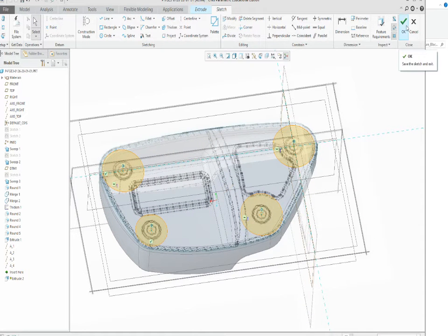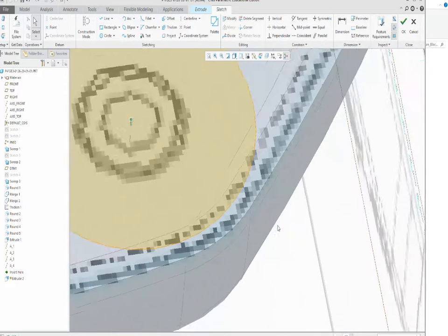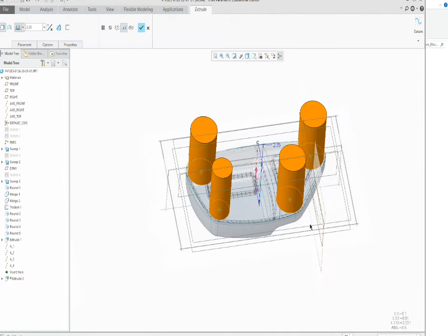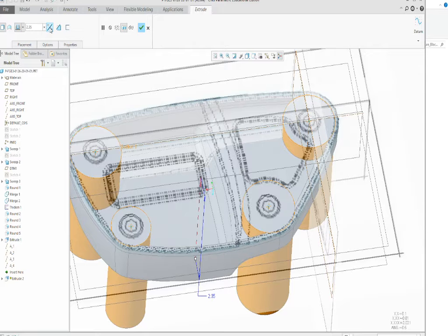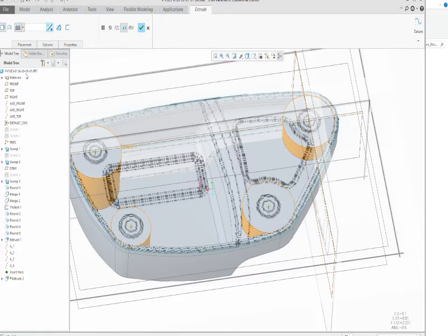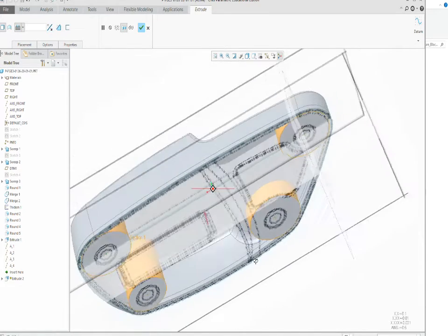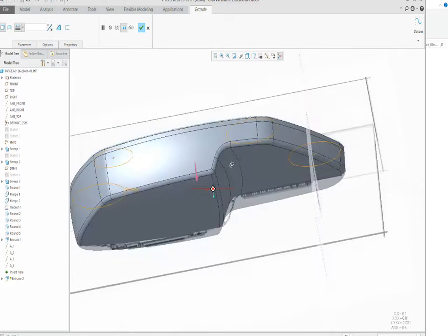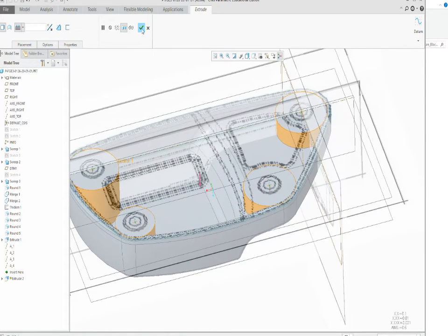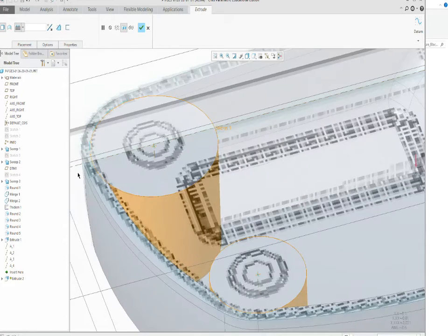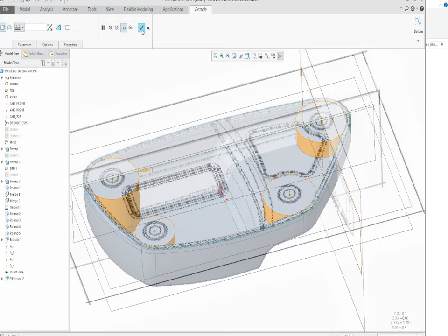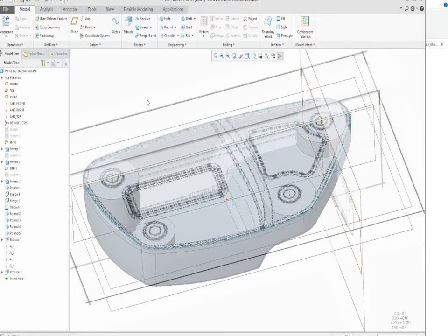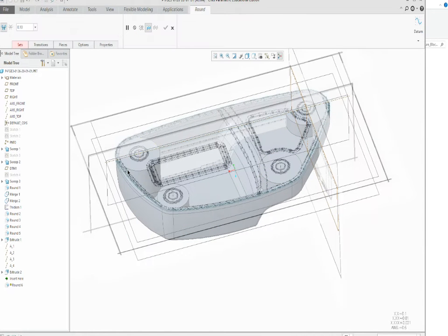Now here's where it gets tricky, is you've got to be inside the wall. And then once you're inside the wall, you start the extrude, you flip the direction, and it is a solid, it's not a surface. On this one, we want to go up to next, which is right there. And what you'll see when it goes up to next is you'll see it kind of close off and not go through the part for your design. If you're outside the wall, you'll see this fill it out there, and you don't want that. Once we've got that into place, now we can run around.